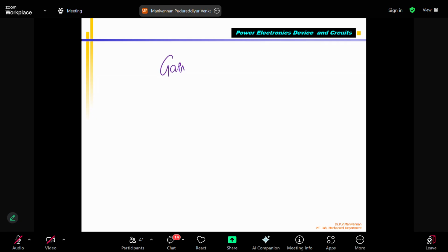Sir, apart from that, why we are talking about gate voltage is that the FET doesn't take current. The current will generally be negligible. So whatever the input voltage, there's no current flowing, so it avoids loading effect, and meanwhile it can also amplify. If I vary the sensor signal, the sensor voltage is connected to the gate voltage. Gate doesn't take current, so loading effect is avoided better than a transistor.